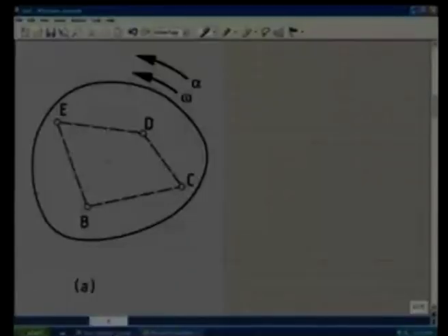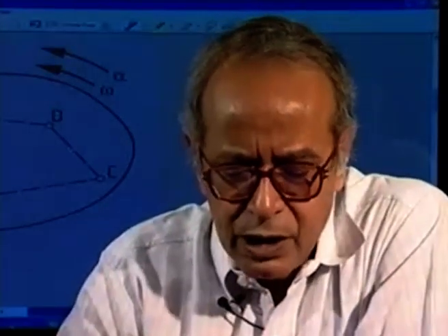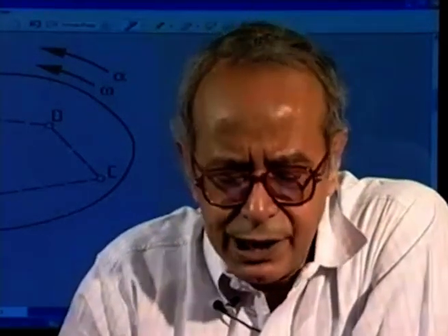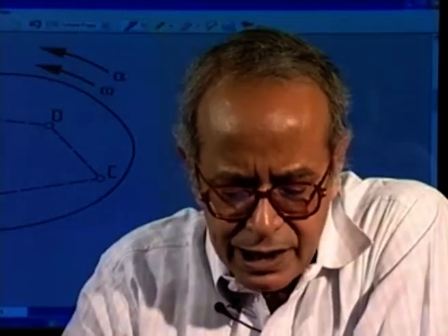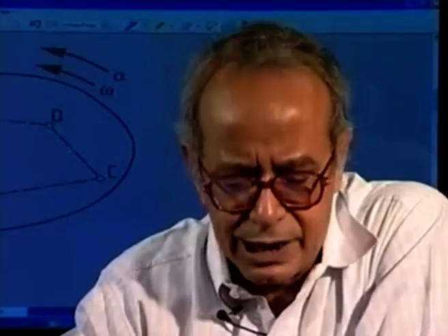Let me now develop this concept of velocity and acceleration image. Towards the development of this velocity image, let me consider a link or a rigid body, say, which is quaternary, and it is connected to 4 other links at point B, point C, point D and point E. The other 4 links which are connected here have not been shown. This is a quaternary link connected to 4 other links at points B, C, D and E. And say the angular velocity of this particular link is omega.